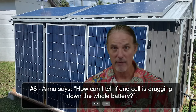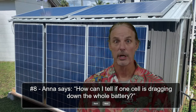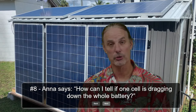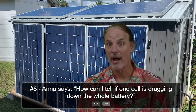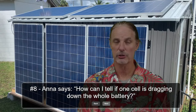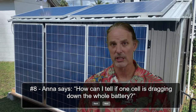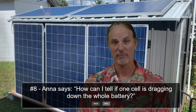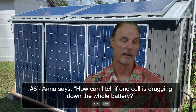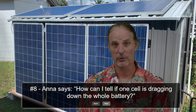And that means that if you do have one that's doing that, signs of that would be that it shows that it's charged before it shuts off, and you see the warning signs of it saying, hey, I'm already charged, when it won't charge all the way. You can't put enough power into it to get it to 100% charge, but you can't bring the voltage up high enough to get it to 100% charge. Those could be signs. If you've got a Bluetooth or something like that where you can get in and see the actual cells themselves, that's your best bet, to look at the actual cells and see if you have one that's running behind. Some batteries are maintainable, where you can go in and you can replace a bad cell.